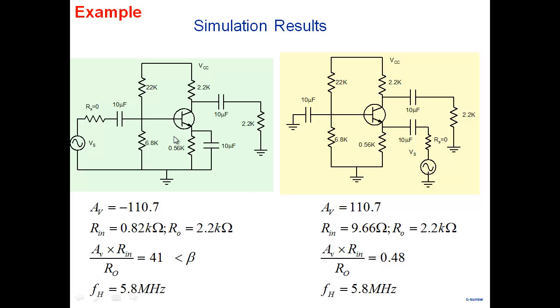This amplifier already exists, right? Common emitter already exists. And you have now invented a common base amplifier. You're very excited, new configuration. And after you evaluate it critically, this is what you see. What will you do with it? What is your judgment? This is what it is giving. Gain 110, Rin very low, Ro same, upper cutoff frequency same, lower cutoff frequency same.